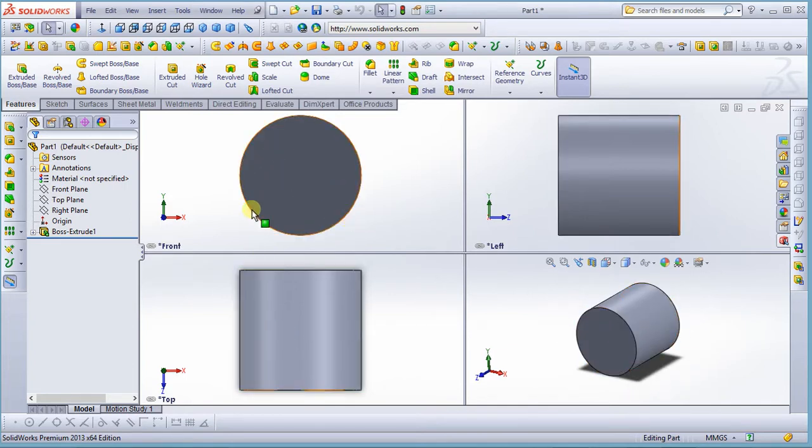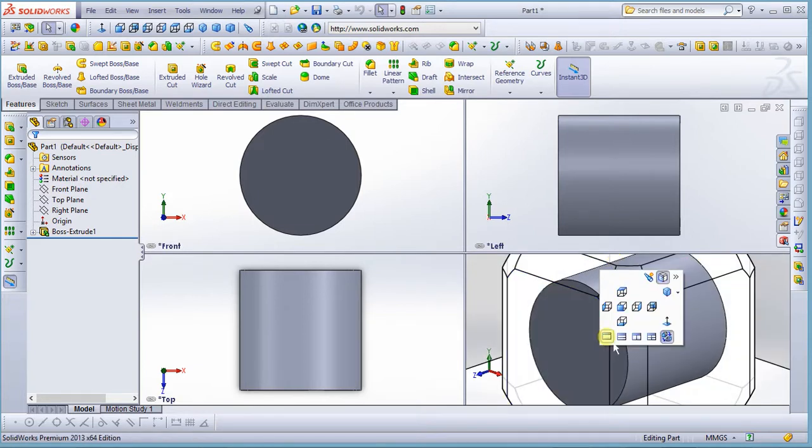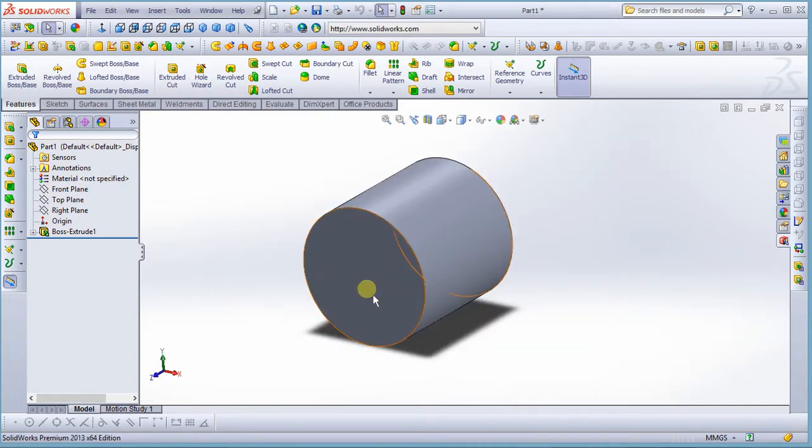This option is provided so that you see how your design looks from different angles. You can see that. If you want to go back to single view, click on that view orientation, you click on the single view, and return to your normal view. This other icon is a view style. The one we are currently in is the shaded with edges view style. I mean our design, the shaded edges have shown.